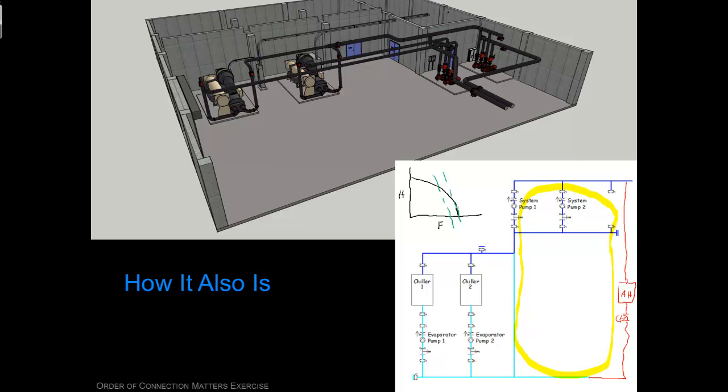Meaning if the pump was out here on its curve and you started throttling it, at first you wouldn't make much change in the horsepower because the brake horsepower line is sort of parallel to the curve. But as you shoved it, this is called shoving it up its curve, as you pushed it further and further up its curve, you'd start to cross brake horsepower lines. So even though you're making more head, you're moving less water, and you win in terms of energy. So throttling will tend to save energy.